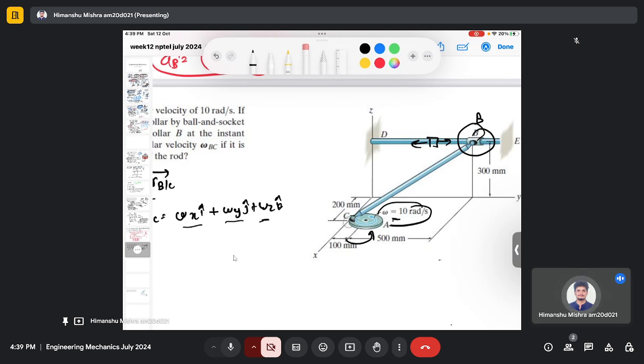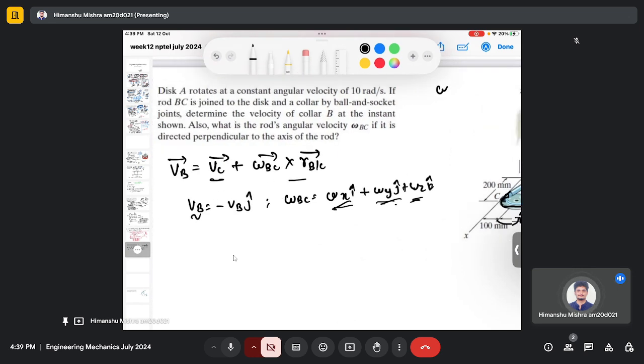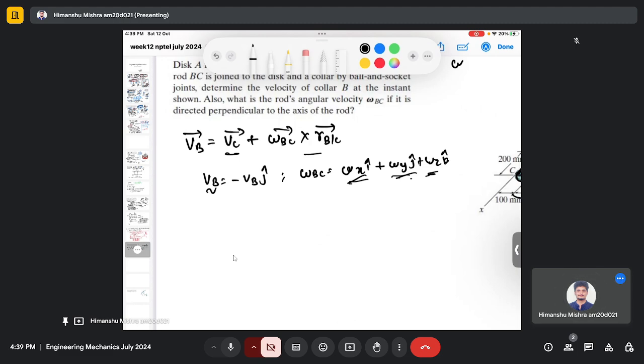But you can visualize here, this disk is rotating one end of this shaft, and this shaft is rotating at this point, and it is producing a translating motion at the other point. So it has some rotation along the x, y and z axes, which is given by omega x, omega y and omega z. We don't know these quantities, and we need them to calculate the translating velocity of point B. So first let's calculate omega x, omega y and omega z.